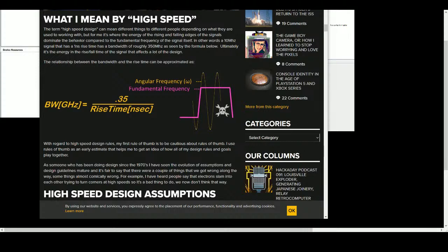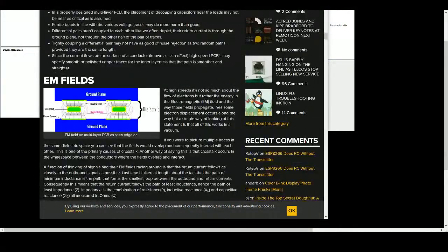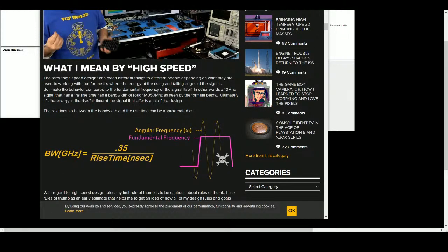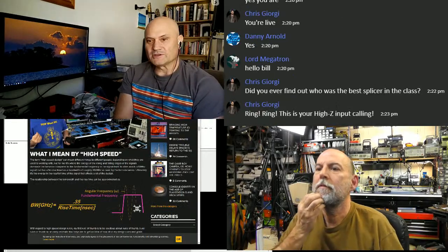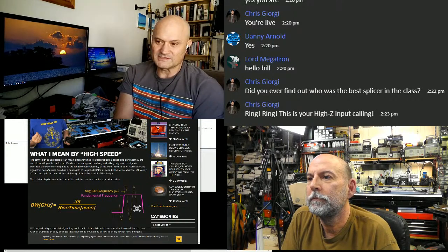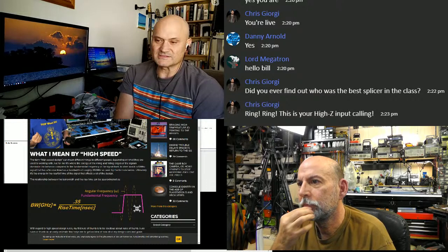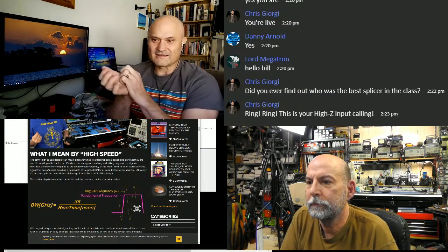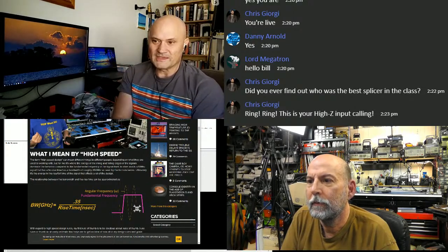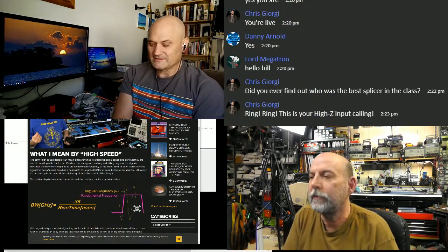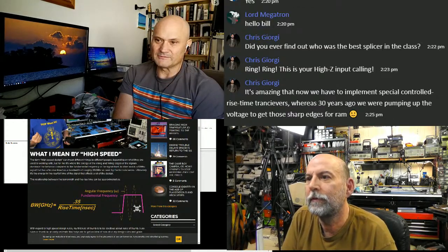Right. And the series termination versus parallel, you could do parallel termination, but the series termination, if you look at an input gate on CMOS, it's still a capacitance, but to those high frequencies, at the higher the frequency, the lower the impedance of the capacitor. Right, right. So to those high frequency harmonics, the input gate of a MOSFET appears like a short circuit. And so the series, different frequencies, yes. The series termination is just a current mode way of controlling that termination.